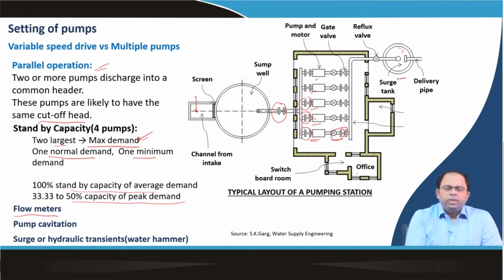We also have flow meters. Flow meters are used to determine the volume of water that is being discharged. So, we meter it at the pump end, and also at the house or residential end, right. When we add up all the residences and we also know how much water is discharged, then we can determine how much water is lost in the system. That is why we have flow meters both at the discharge part in the pumping station as well as in the houses.